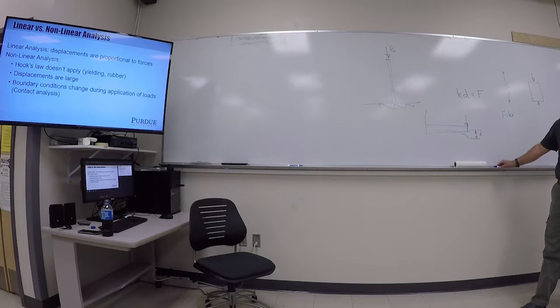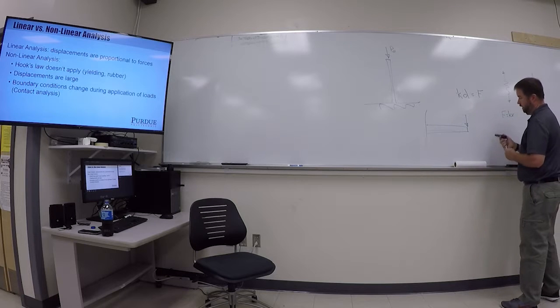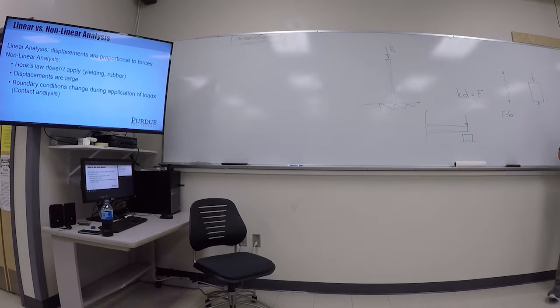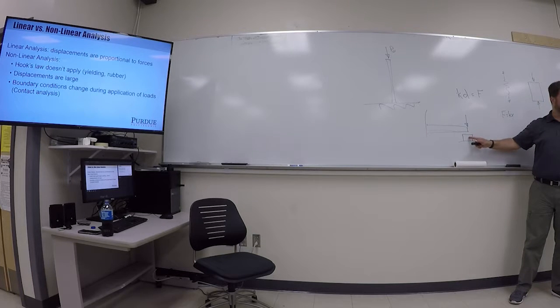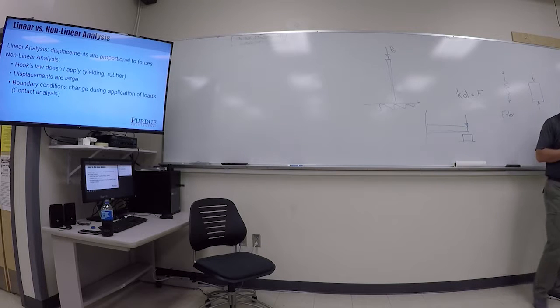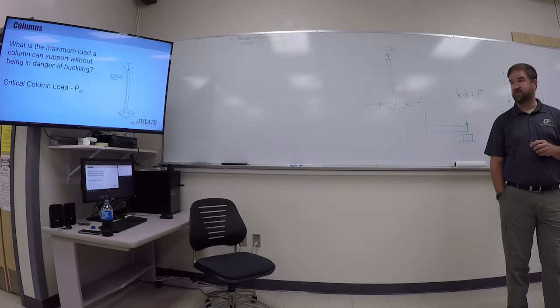The last thing there for nonlinear analysis is boundary conditions that change during the application of loads. Maybe a good example of that would be, what if I have a beam that is bending and there is something sitting just below it? So I apply this force, it bends down and it starts touching this piece down here, and all of a sudden I've changed from a cantilever beam to something that has a simple support on this side. My boundary conditions have changed in the middle of my analysis. And if that happens, that's not something that we can approach with a linear program. So contact analysis, where bodies deflect such that they come in contact with other bodies, would be an application of a nonlinear analysis package. So just be aware that those exist.